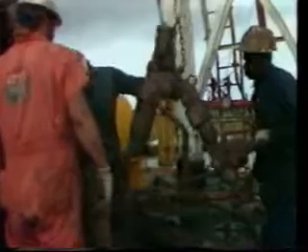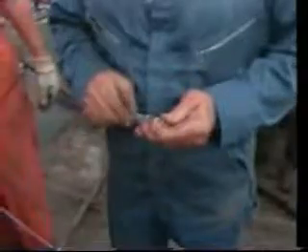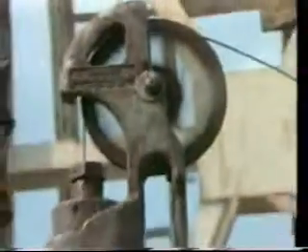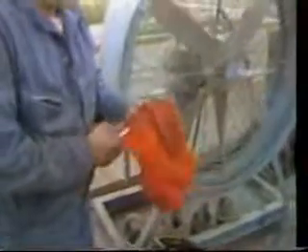Both the inclination and the direction of a well bore are obtained with a magnetic survey device. This tool is run inside the drill pipe on a wire line when the drill string is stationary. And a built-in timer actuates a camera which records a compass bearing at the bottom of the hole. When the tool is retrieved, the reading can be plotted on a graph which shows the path of the deviated well.